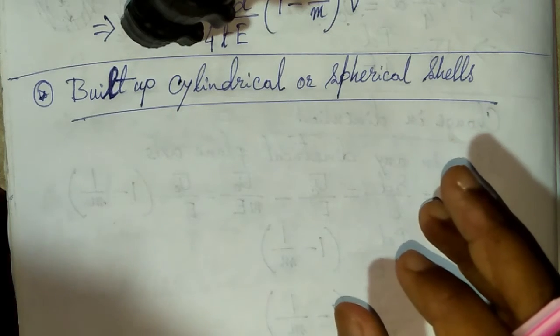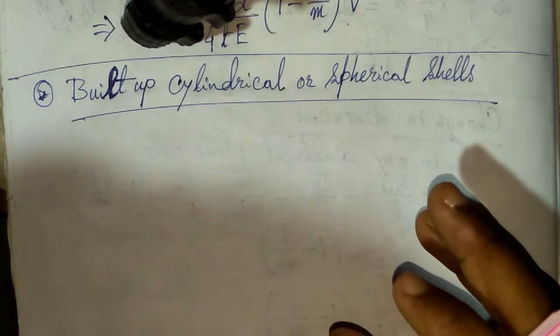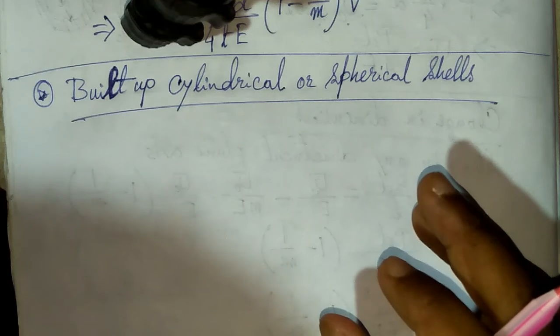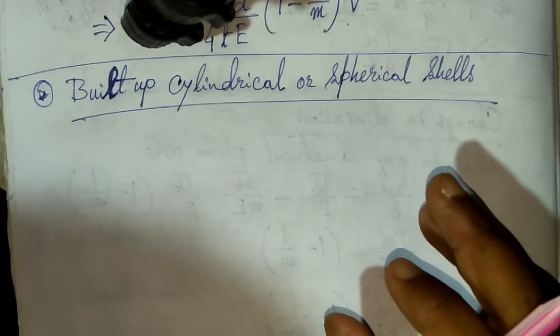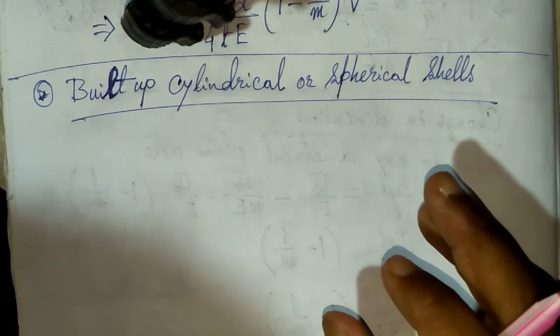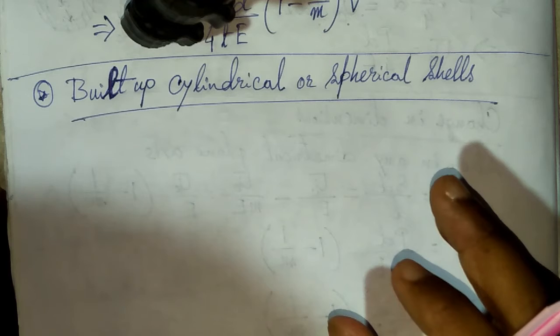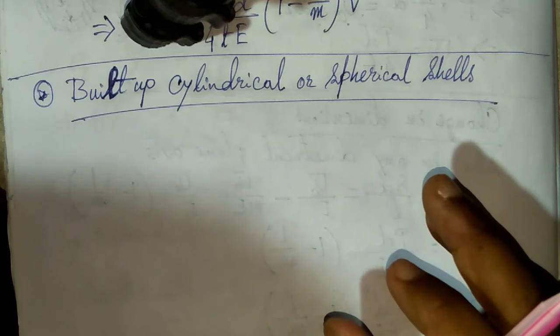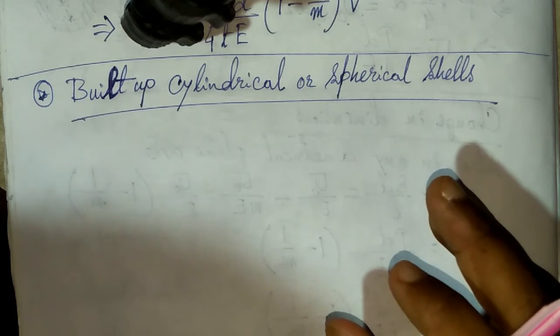The longitudinal joints reduce the resisting strength of the shell plate against bursting, and circumferential joints reduce the resisting strength of the plate against the tearing due to the pressure on the end plates.